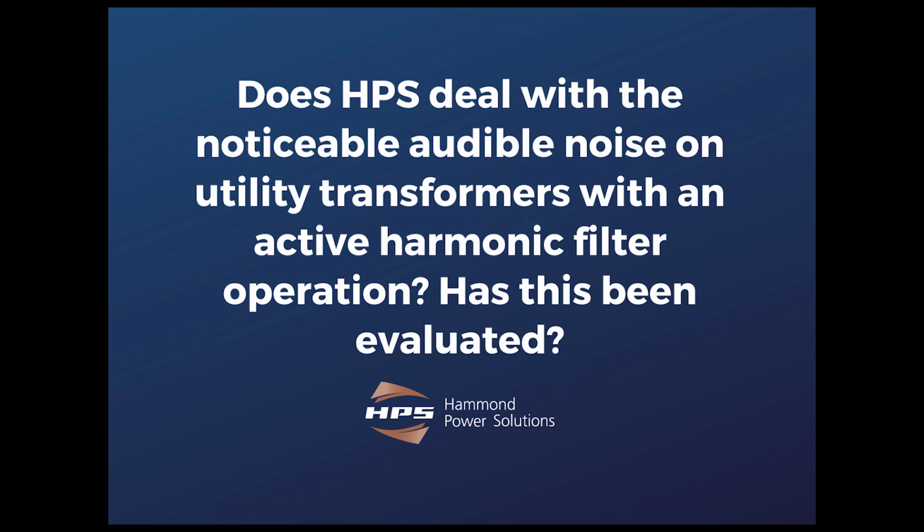The core will be vibrating at twice the frequency of 60 hertz, and that's by far the biggest component of the noise of a transformer core. The higher frequency harmonics are a component, but typically much smaller, and oftentimes the major component of audible noise is caused by something other than harmonics. However, again, we have not evaluated that question specifically.